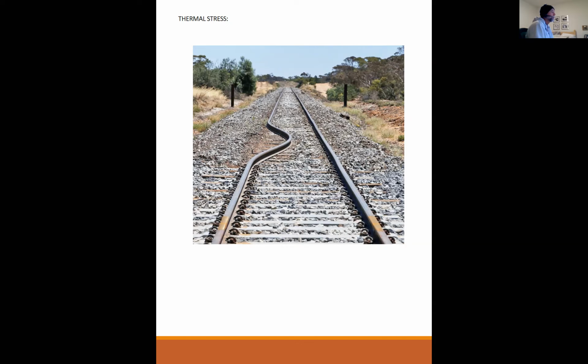So we talked about Hooke's law. That's a real basic one. Hooke's law: stress is equal to strain times Young's modulus. We talked about what stress is. Stress is force over area. What is strain? Strain is the new length minus the original length, over the original length. Those are the basic concepts. There's only so many ways that I can try to trip you up in a problem when we're only drawing from those very limited handful of principles.